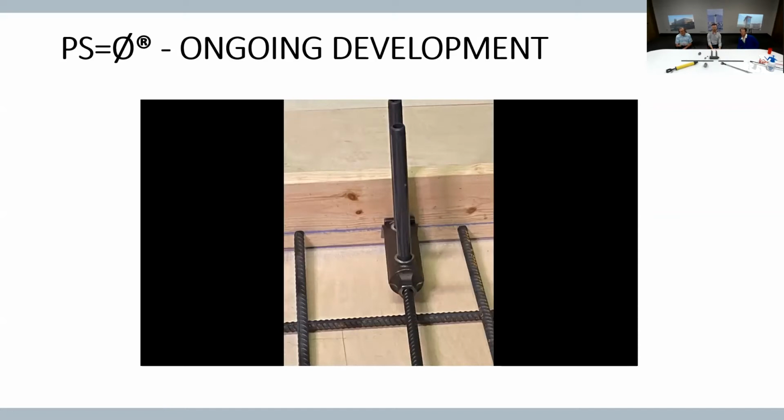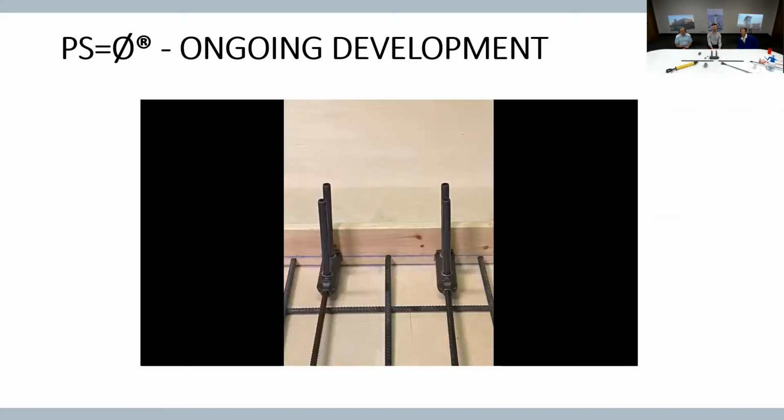They're a Schedule 40 pipe, so they're pretty stiff. And so this process, we've just found this from the contractors, what they like to do for these installs. And we've also found a solution, I will go to that, on also our V-joint. We'll probably get to it here, but we found something from a control joint in sheetrock. A good friend of mine with Perini actually told that to me while I was discussing with him. And we just got some samples in today, in fact, and it looks perfect.